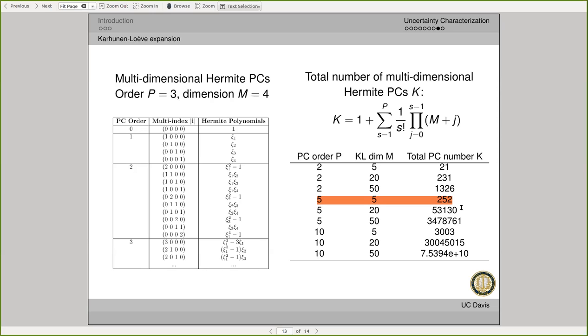If you had, for example, a small finite element system with stochastic elastic finite elements that has 1,000 degrees of freedom, and you do this expansion of the input random field into Karhunen-Loève of dimension M5, and expand into probabilistic space with polynomial chaos 5, you're actually going to end up with 252,000 probabilistic degrees of freedom, for the original 1,000 degrees of freedom, 1,000 nodes, let's say for a 1D shear wave or something like that.